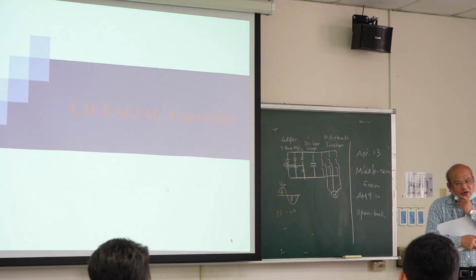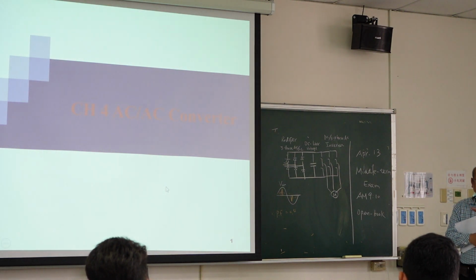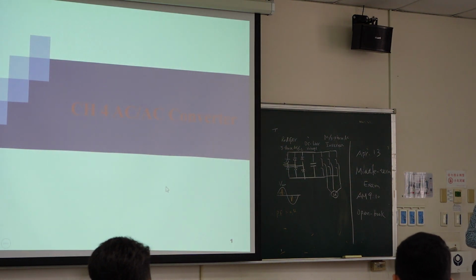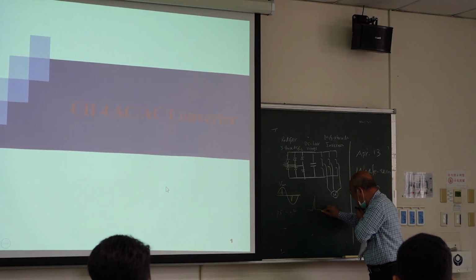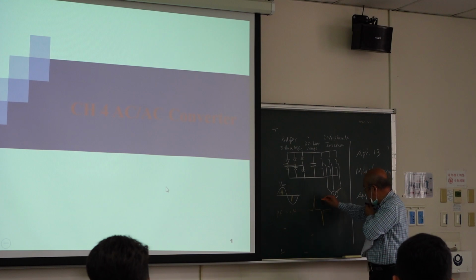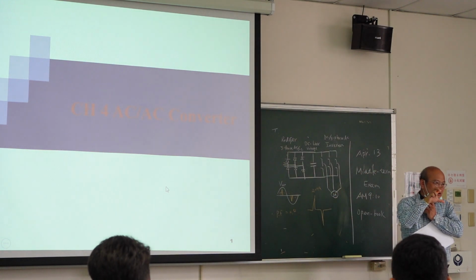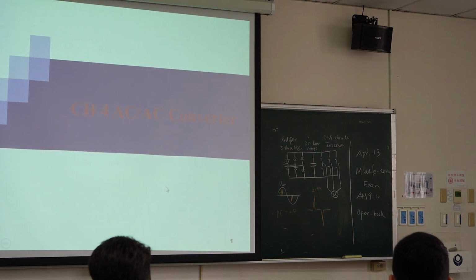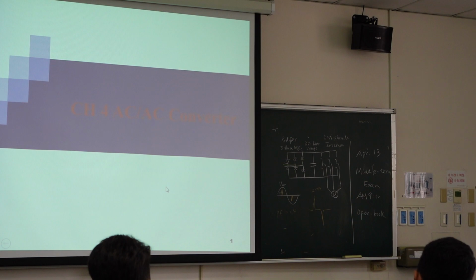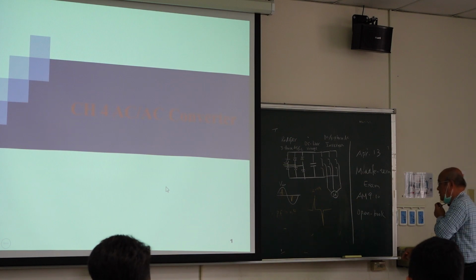So do you think that this is good? If you have power factor 0.4, if you have this waveform, and this could be 200 ampere, because it is a huge drive system. Do you like this circuit? You say no, it is not good. So how can I improve the power factor?